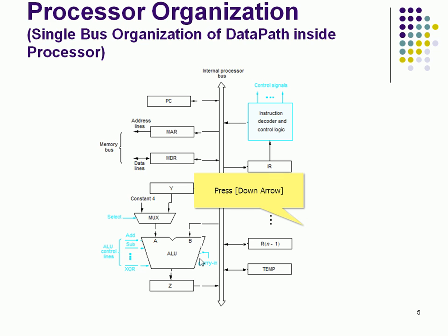Once the control signals are decoded from the instruction, they are connected here. After understanding the instruction from the IR, we can understand what arithmetic or logic operation is mentioned in the instruction. That signal will be connected here, and according to that, the arithmetic or logic operation will happen. If it is an addition, then the carry will be required, so that carry will be considered. Finally, the Z value will be produced, which approaches the bus.